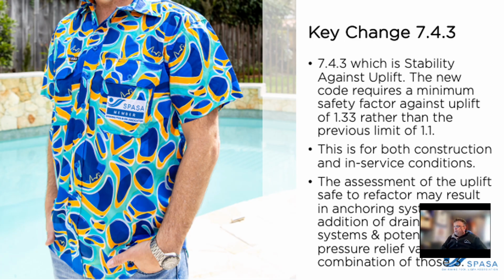The assessment of the uplift safety factor may result in anchoring systems, additional drainage layers, and potentially pressure relief valves, or any combination of those three. This will be, again, the judgment of the competent person.